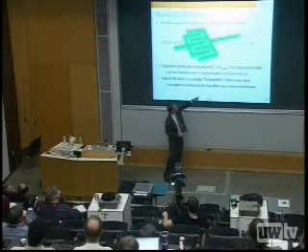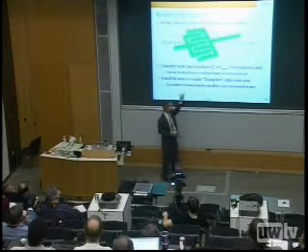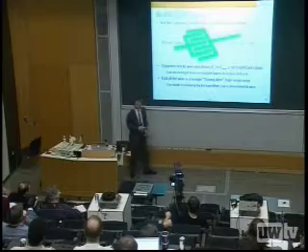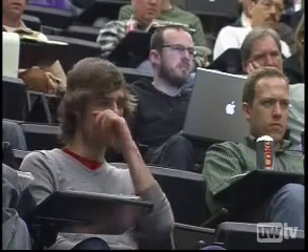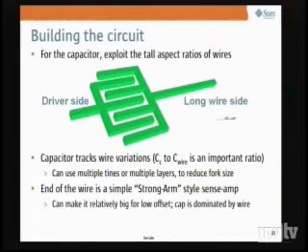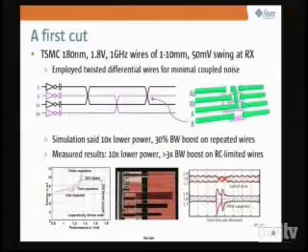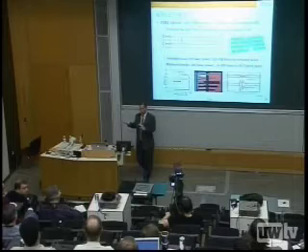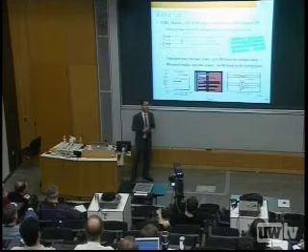And at the end of this is an amplifier. And I don't show it here, but it's again a StrongARM style sense amp. One benefit here is that the amplifier at the end can be relatively large because its capacitance is swamped by the wire capacitance, and so it can have relatively low offset. All right, so this all seems to make sense. We went and built a chip. This is back in 2005. It was a 180 nanometer technology, and we did up to 10 millimeters long wires, running about 1 gigahertz, and trying to get 50 millivolts of swing at the receiver.